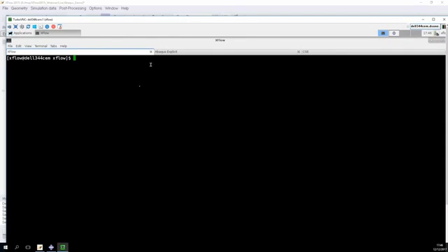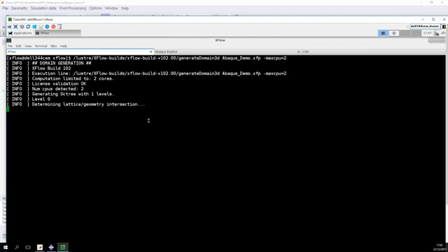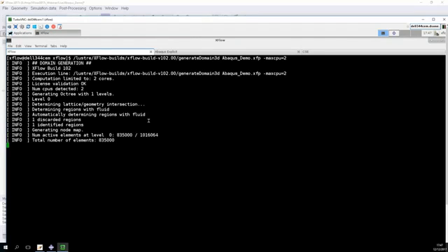So we're going to have three windows open: XFlow, Abaqus, Cosimulation, and we're going to see how to do each step. First of all, we're going to generate the XFlow domain, which is the lattice discretization. That's the discretization of the volume we're going to analyze. That is completely automatic, so it takes a few seconds.